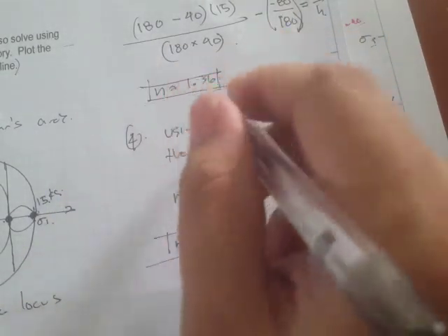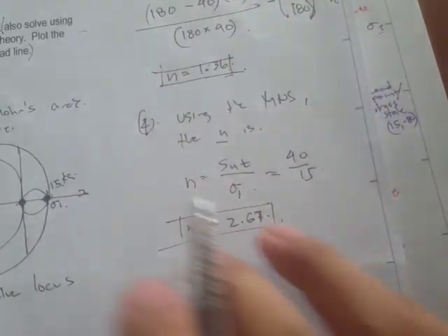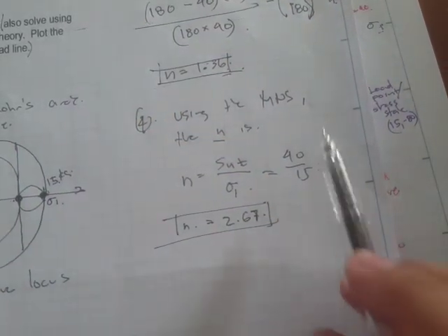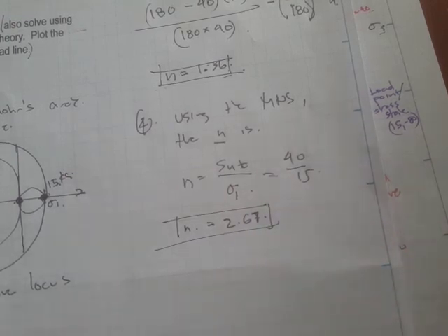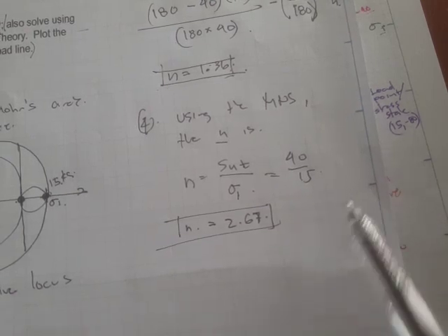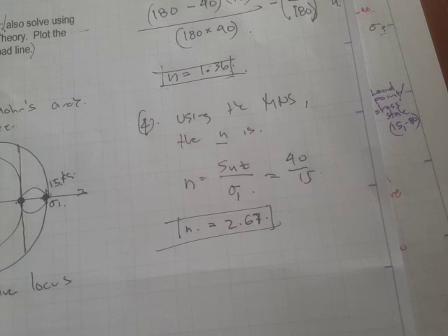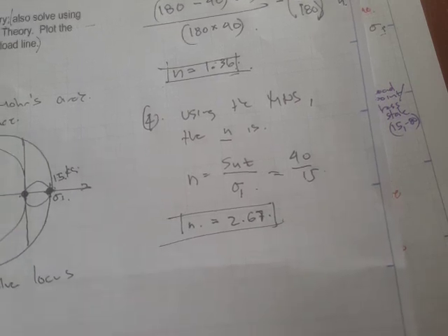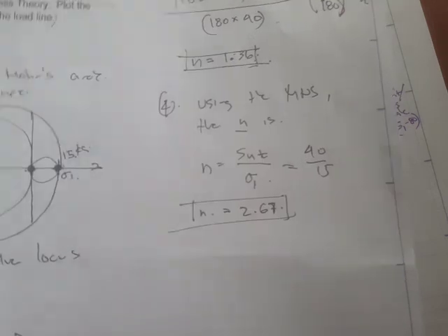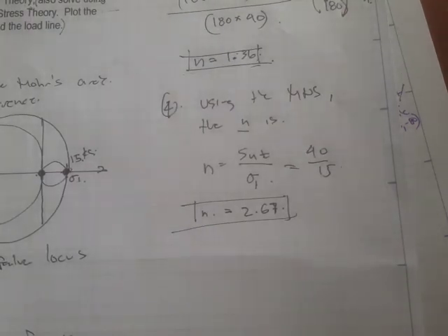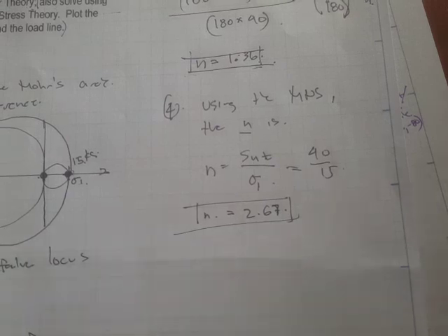And we see we have different values for the factor of safety when using modified Mohr and when using the maximum normal stress. By the way, the maximum normal stress is not preferred. It's just included in the references for historical reasons. So I think that's all for this video, and in the next video we will continue our discussion about failure theories for ductile materials, and we are still in static loadings.